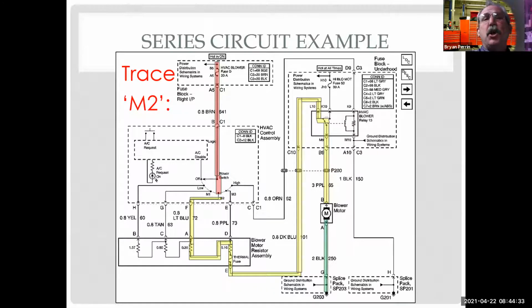And this is huge, because this is why people really struggle diagnosing electrical problems: we backfeed on parallel non-connected circuits and we see voltage in places that confuses us. If you're struggling with the concept, and you have a voltmeter and any kind of light bulb load, put one wire to the positive battery cable, don't connect the other end, and take your meter and see the voltage there, and you'll see what I mean. Then connect it to negative, and you see you no longer have voltage there, because now the bulb would use all the voltage.